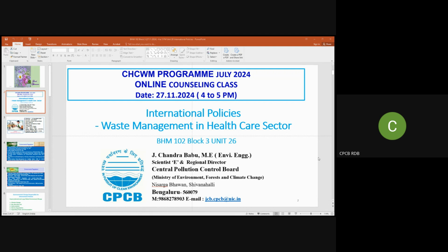In the case of non-bedded hospitals, the quantum of wastewater generation will be very small. Therefore, the rules suggest that such hospitals can collect the infectious liquid waste and treat it with a chemical disinfectant, using 1 to 2% sodium hypochlorite solution containing 30% residual chlorine for at least 20 minutes. Then the treated wastewater can be discharged into the drain. This is in a nutshell.